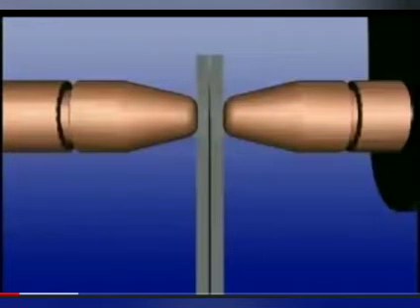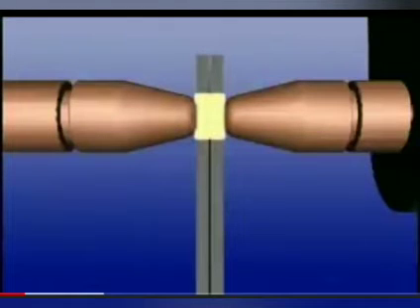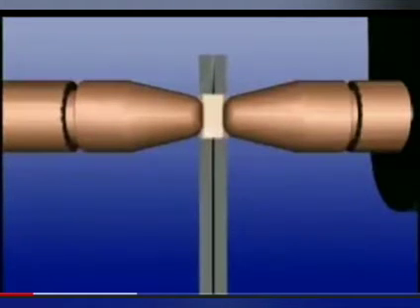Steel is a very poor conductor of electricity, and it will resist the weld current as it flows from the spot welder. The friction created by the current forcing its way through the metal heats the weld area to over 2,000 degrees Fahrenheit. The squeeze pressure from the weld electrodes now compresses the molten area and fuses the two metal surfaces into one solid nugget.